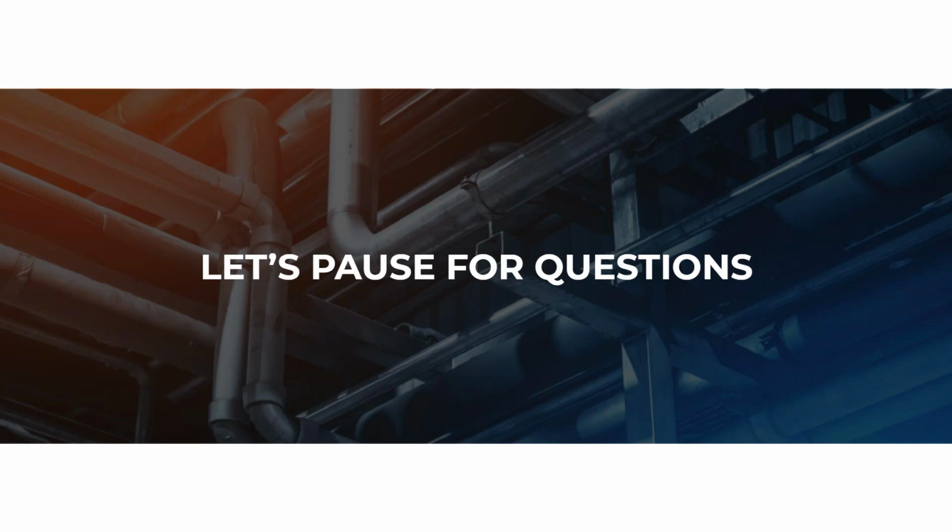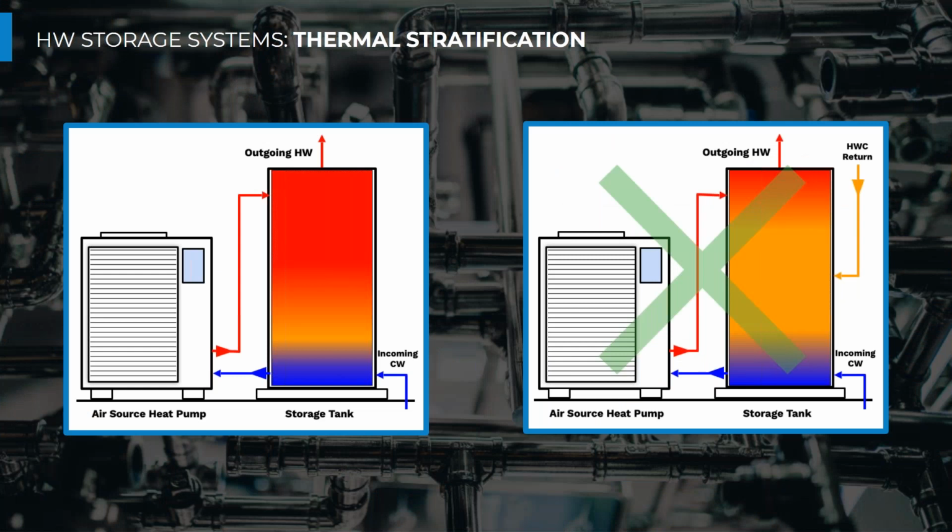Got it. And then someone else asked, can you tie the return water to the cold water to still allow for stratification? You can tie it to the cold water, but it doesn't help in your stratification because we actually end up mixing more of the tank. If we essentially took this pipe and connected it here, then we'd pull that yellow down further. We'd have warmish water at the bottom of our tank. We'd still be pushing water in here, and therefore it's got to go out, and it's going to go out here. So that's our mixed area.